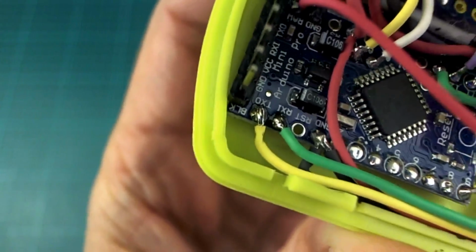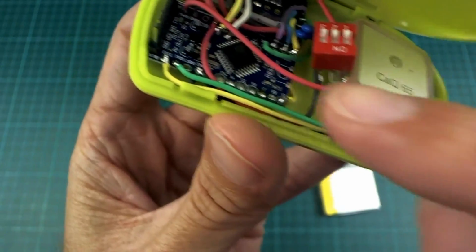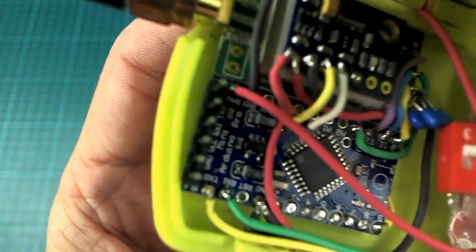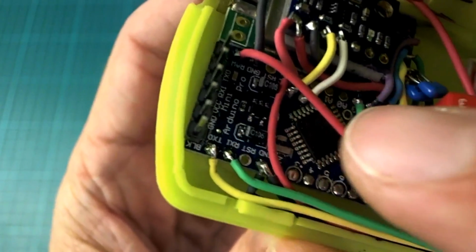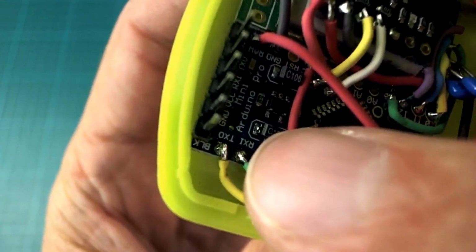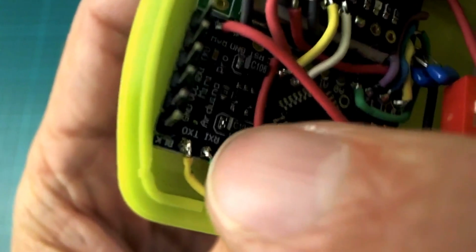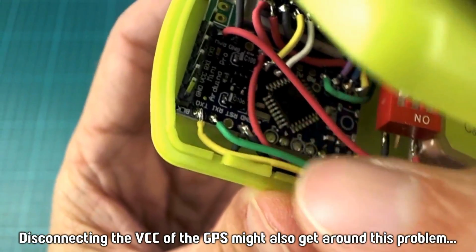So one of the downsides with connecting to the RX and TX pins like that is that when you power it up, the GPS is going to be talking to the Arduino, sending it information. So if you want to connect your computer, or you want to upload the sketch onto your Arduino again, it won't work. Most likely it won't work. So I've found that whenever I want to upload the sketch onto the Arduino, I have to disconnect the RX pin, I think. One of them anyway. I think it's the RX pin you need to disconnect, just temporarily, to upload the sketch.